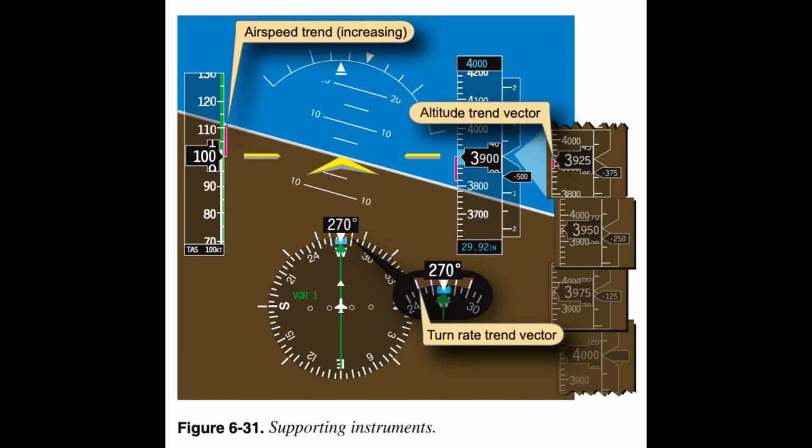The airspeed indicator depicts an increase if the pitch attitude is lowered. Conversely, when the pitch attitude increases, the pilot should note a decrease in the airspeed. Primary bank.